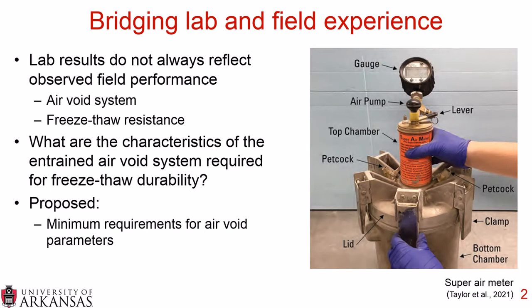And they looked at two different questions. First, they looked at the minimum requirements for air void parameters in concrete pavements. And then second, they looked to modify AASHTO test methods in order to better capture these field performance linkages to lab results.